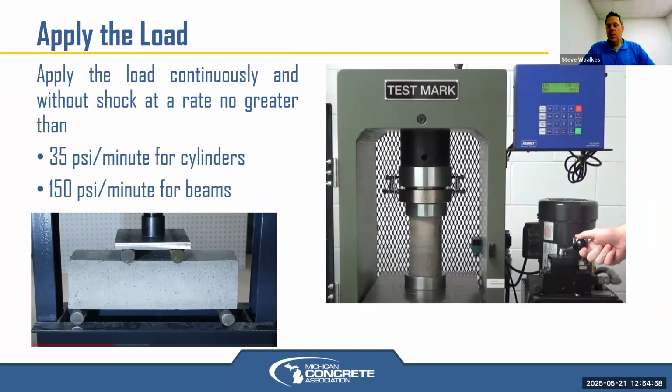Applying the load depends on if you're doing a beam test or a cylinder test, and the computerized ones accurately bring up the load within the required time frame. They don't overload, and it's continuous. The computerized ones are nice, especially the ones that have a pump integrated, because it's consistent and constant versus the hand pump. You're actually loading and then not loading every time you retract the handle of a pump. So there's some debate as to whether a hand pump is continuous or not.